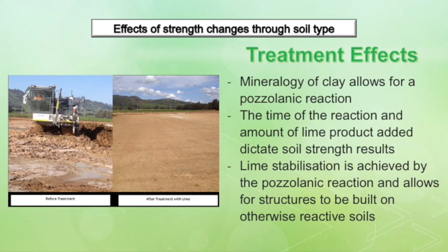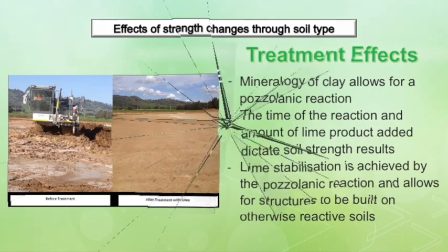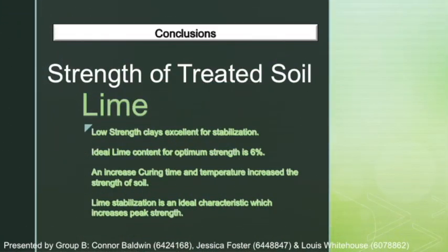It is imperative that soil strength be considered when determining the suitability of a soil for construction to ensure a safe and durable design. Introducing lime to reactive soils is an effective strategy to ensure otherwise low-strength soils meet design requirements. Low-strength clay soils are excellent candidates for lime stabilisation, as minerals in the clay react well with the lime to form cementitious products that bind the clay particles together, increasing strength.